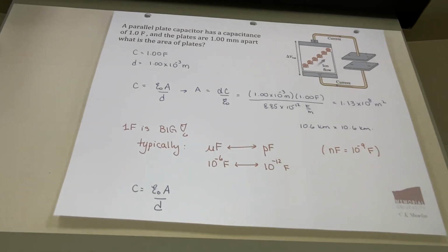If you wanted to put this in your cell phone, it would be difficult because it's bigger than your phone. So something you can do to deal with that area is insulate the outside of the plates as well and roll them up. This would interest people who are curious how you make things like this, which is definitely the kind of person I am. You roll them up, and all of a sudden you get a smaller device which fits inside stuff. That's why the capacitors you see inside circuits, probably the ones you use in the lab, are all round, right? It's 2 metallic sheets, a dielectric between them, all rolled up. It gives you a bigger area for a physically smaller device.